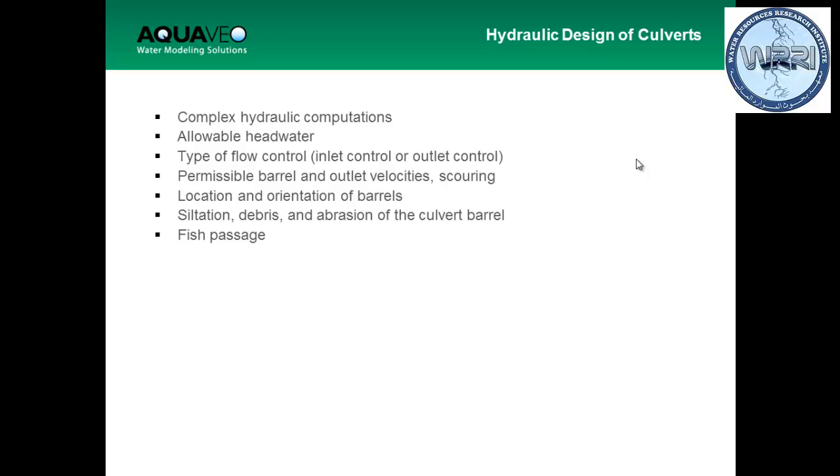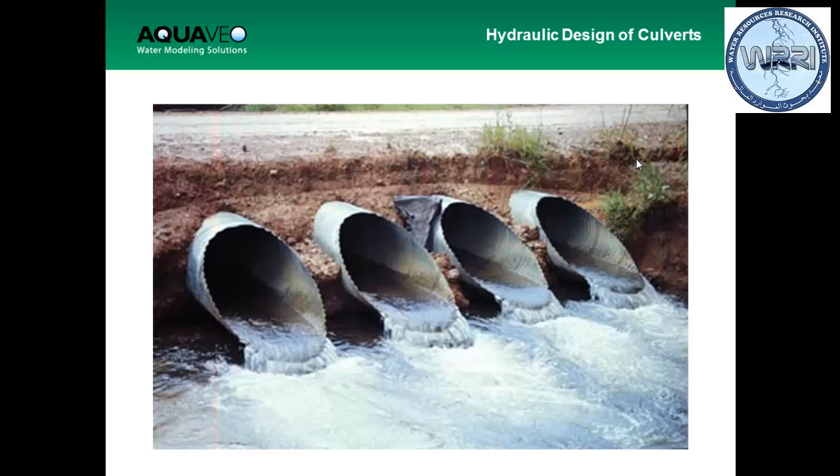And culvert analysis is a little bit different than regular hydraulic analysis, regular open channel, because you have different situations. One part of culvert analysis is there are two situations you can end up with. One situation is you can have inlet control, and that means the water above the culvert, the water in front of the culvert, is controlled by the inlet. And the other kind of condition you can have is called outlet control. That means the water is controlled by the outlet depth, or the depth of the outlet. And there are different orientations of culverts you can have, and different things to consider.